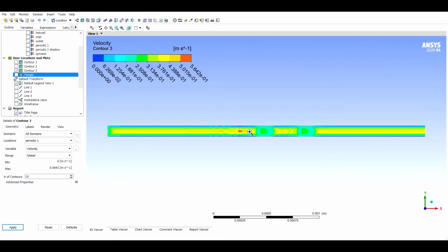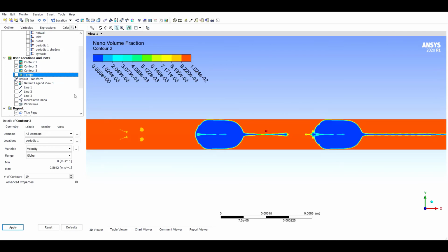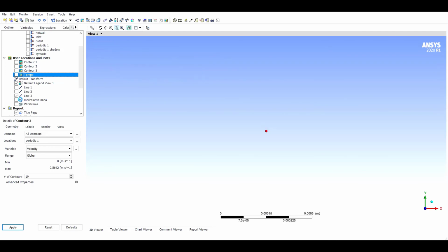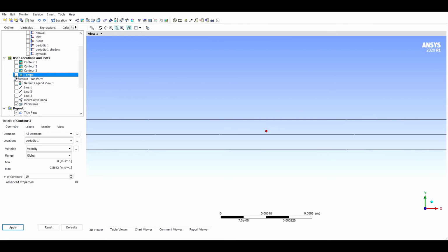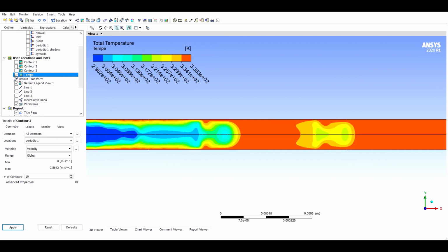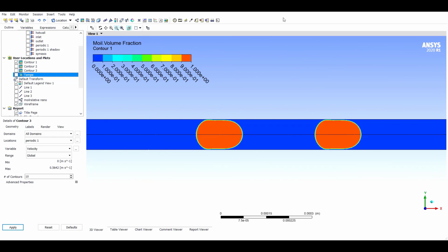So, when we analyze these results, we can see that although increased internal circulation and thermal conductivity have improved heat transfer performance, there are limiting factors such as increased pressure drop. So, it is very important to identify the better flow parameters for effective and efficient heat transfer.